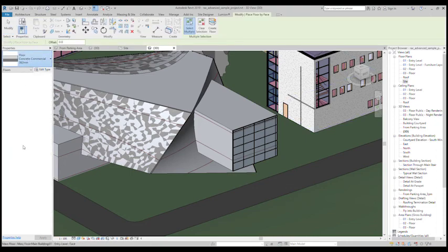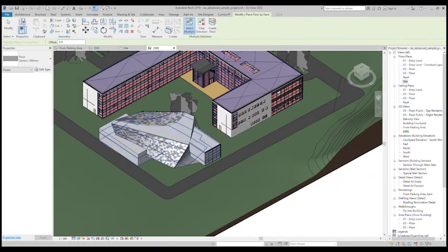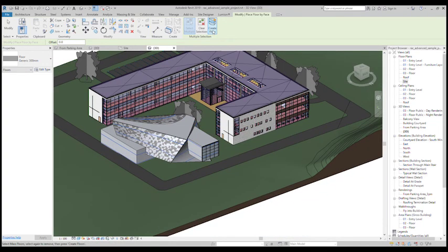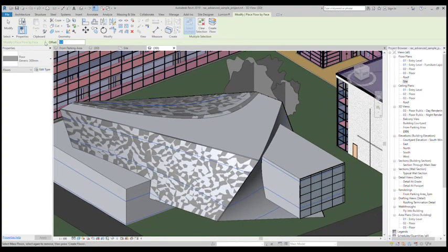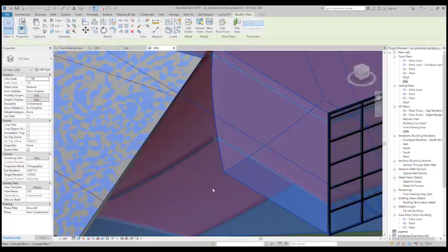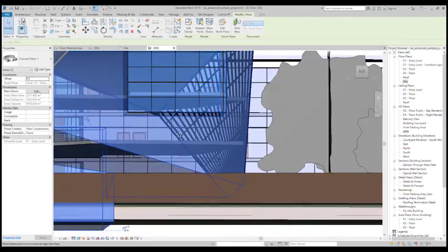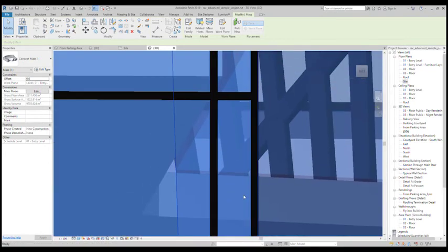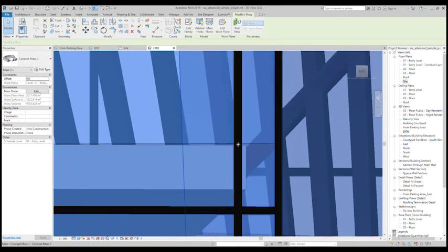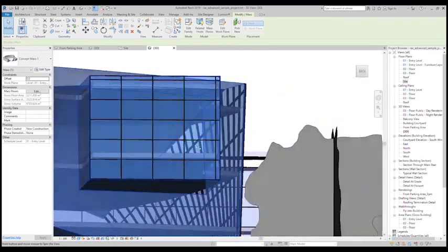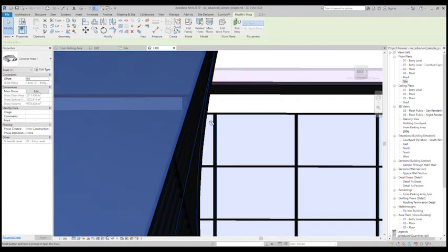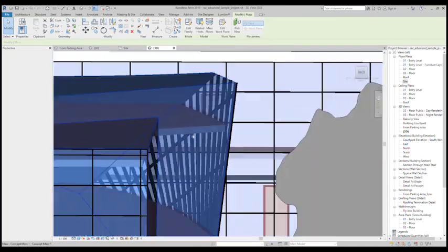200 or 300 thick. I'm going to select those mass floors and look, before I say create floor, I have the preloaded offset option. So now if I click on that, 230, and say create floor, it creates all of the floors with a preset inset. Can you guys see? There you go. So there's the mass floor, the red analytical floor that we see there, and that's the inset concrete floors. So that means that our floors will not go to the edge or past the edges of our walls, and it won't look messy.